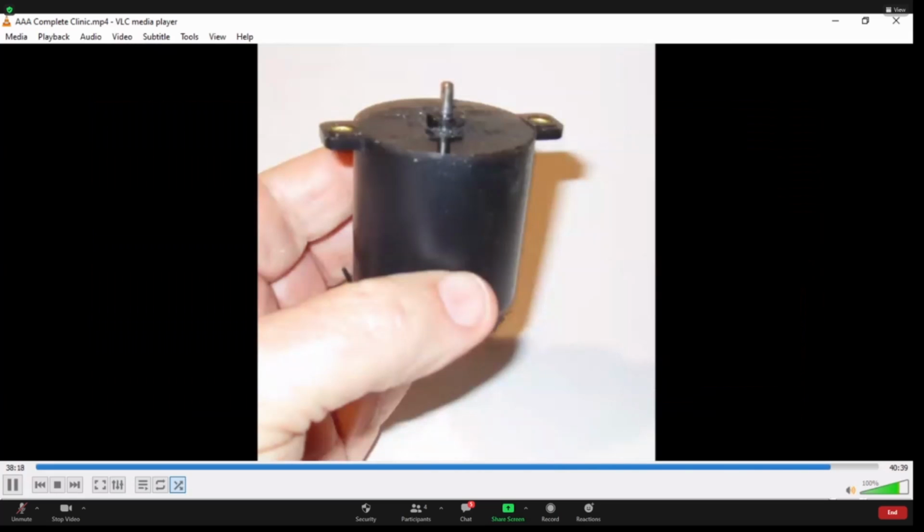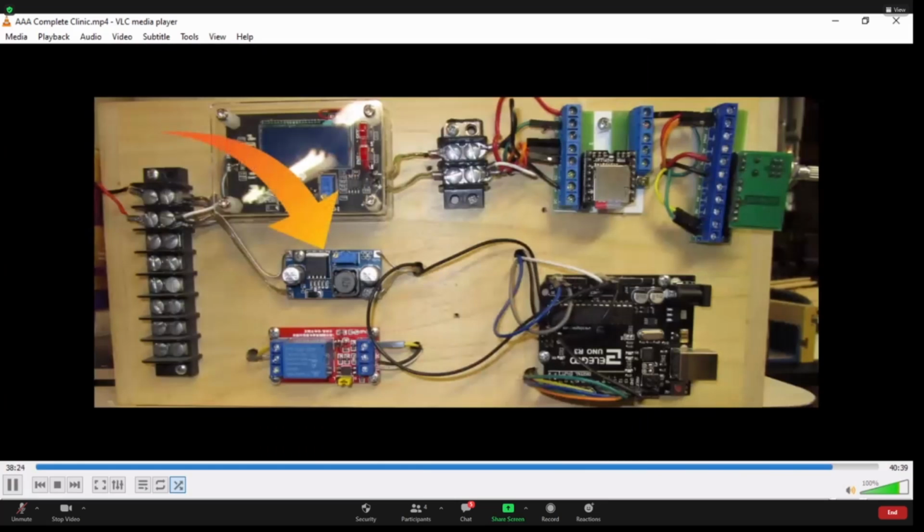It uses a single 12-volt Hankscraft motor to drive the Carousel, but requires a second buck converter to drop the voltage to where the carousel is spinning at a safe speed. I added a wire from pin 16 of the MP3 player to pin 9 of the Arduino. Although not needed for earlier projects, this wire tells the Arduino when a song is finished. When a song completed, I used a relay controlled by the Arduino to stop the carousel's motor.